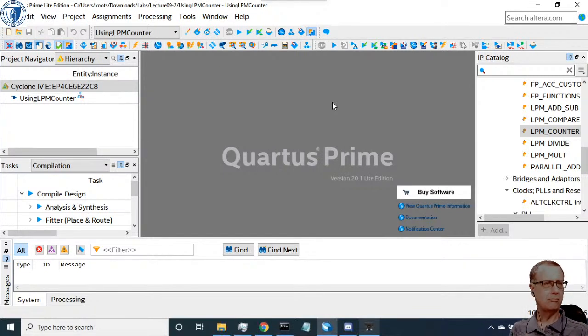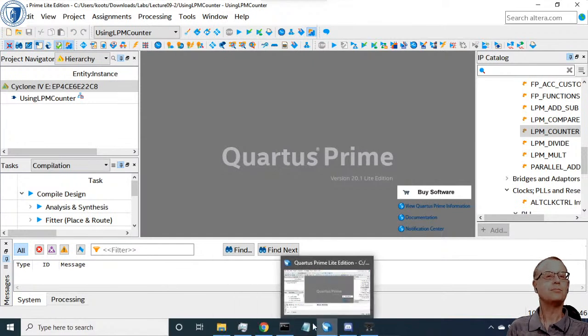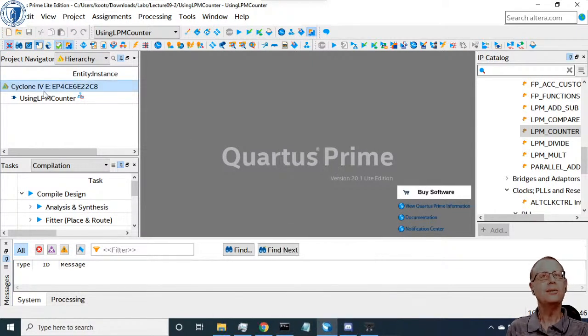I am not doing a good job of this this morning. I apologize. Too much other stuff happening. But anyway, the idea is that that counter is now a 26-bit counter, and it is a modulo 50 million counter. The input is a clock.